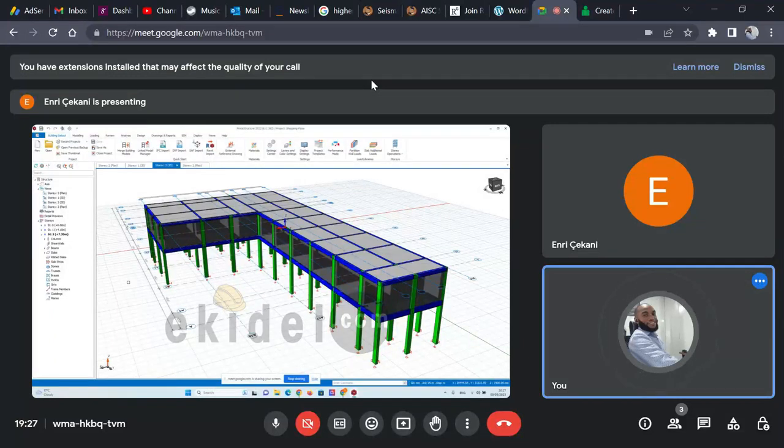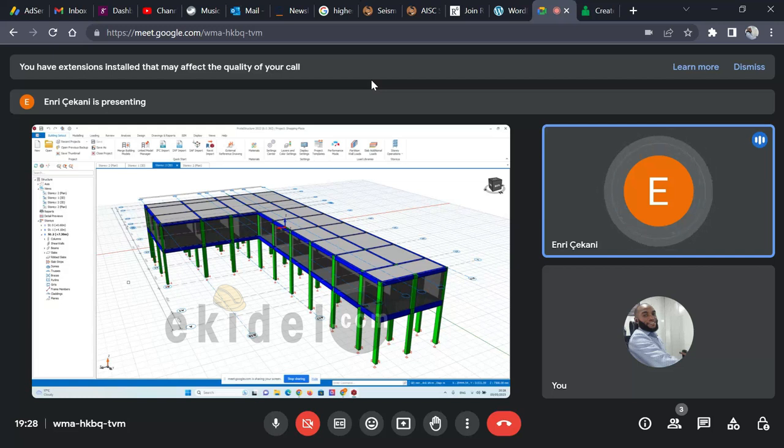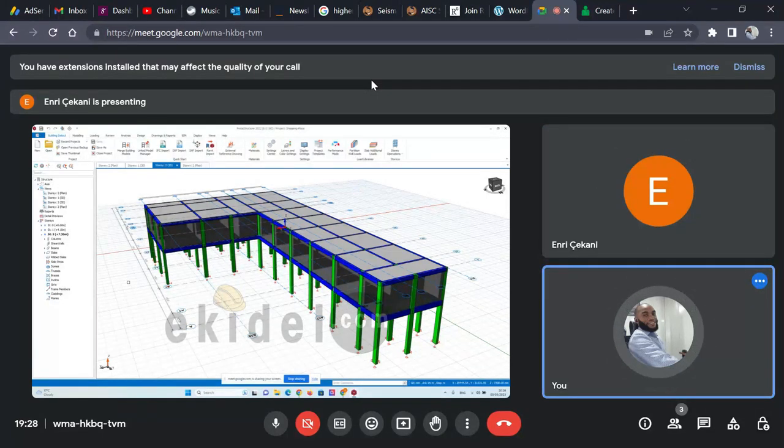So when you are designing that beam, you have to design it very well as a confinement element, or let me say member, because you are practically respecting, let's say, the critical zone in a column, but even the beam has critical zones. So we use strong confinement on that. That is for this increasing of capacity. Then there are factors contributing to confinement. When you talk about confinement, there are some factors you are meant to consider. One is the link and bar spacing, either for the beam or anything. You must consider the link and bar spacing. You must consider the link and bar diameter.